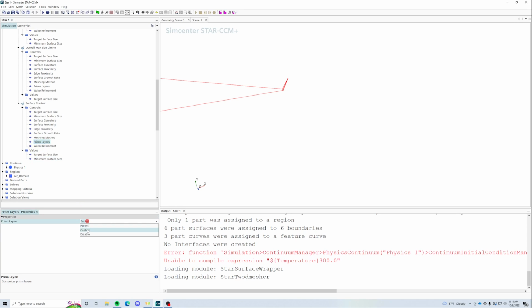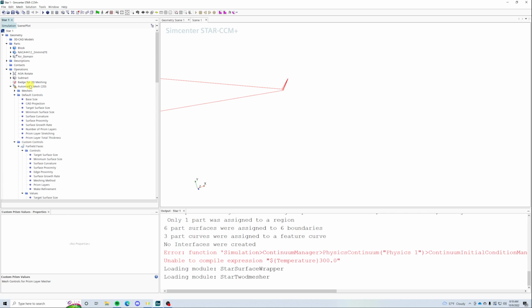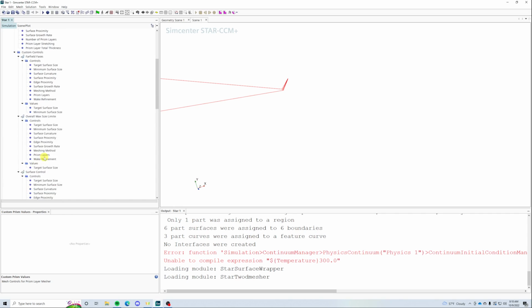We're also going to change up the prism layers. We're going to reduce the prism layer thickness. Even that might be too much. Remember, this is a 2mm radius, and the prism layer is in this position 2.5mm thick. That might be a bit much, so we're going to reduce this to 18%. That's probably reasonable-ish.